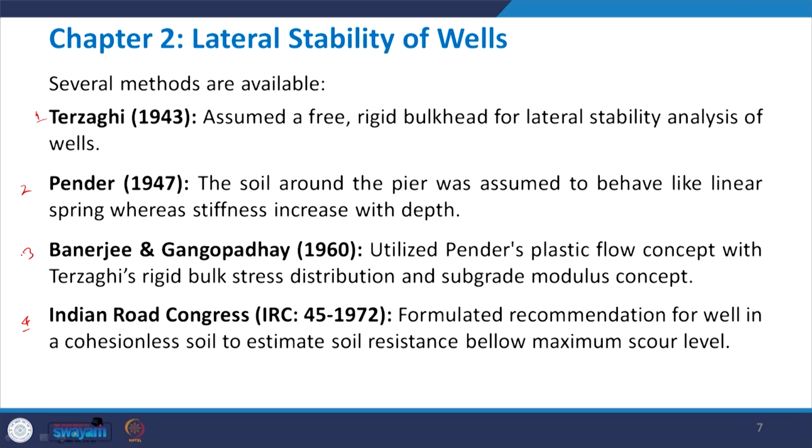Terzaghi assumed a rigid bulkhead for lateral stability analysis of wells. So, first of all, a rigid bulkhead has been considered for lateral stability. Then Pender extended the analysis of Terzaghi, where the soil around the pier was assumed to behave like linear springs, with stiffness increasing with depth. So, rather than assuming a constant, they have replaced the soil by springs.